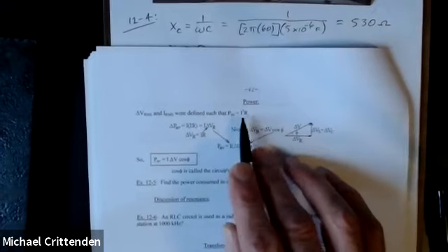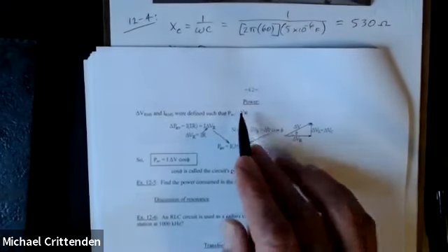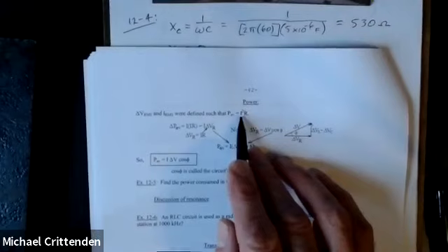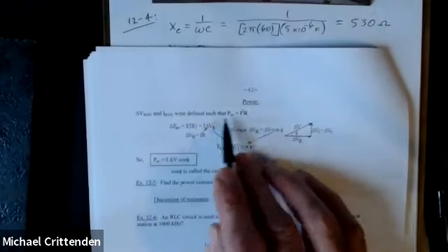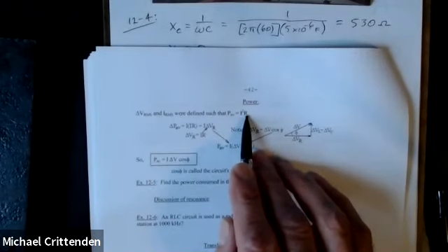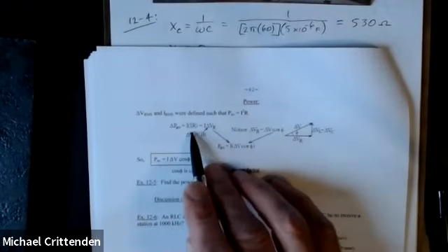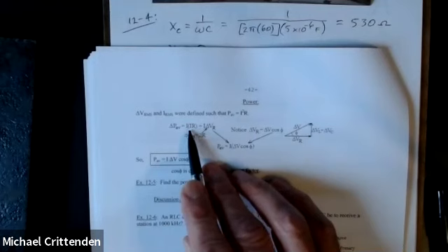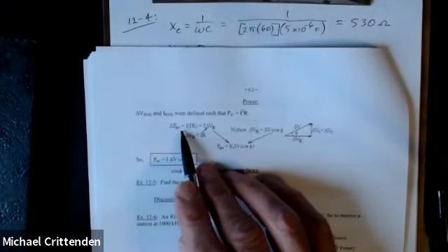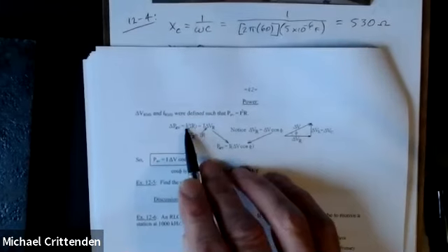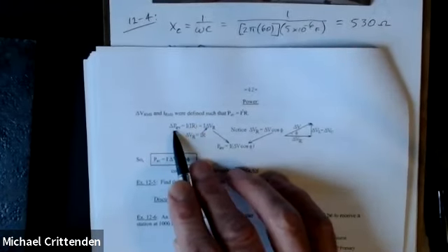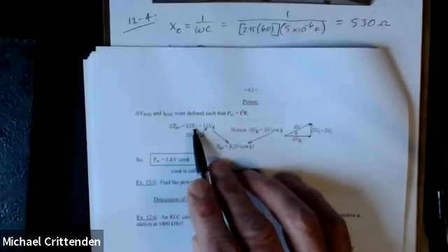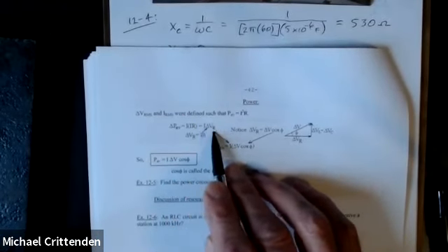Power is equal to I squared times R. Well, let's take it a step at a time. I squared, I divided it up into I times I. So I squared times R, average power. I times R is equal to the voltage across the resistor. That's Ohm's law.